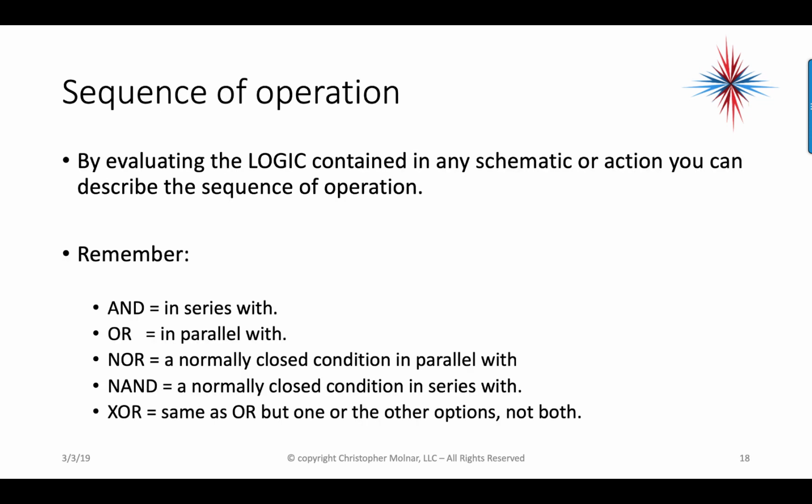By evaluating the logic contained in any schematic or action, you can describe the sequence of operation. Remember, AND is in series with, OR is in parallel, NOR is a normally closed condition in parallel with. NAND is a normally closed condition in series with. XOR is the same as OR, but one or the other options, not both.